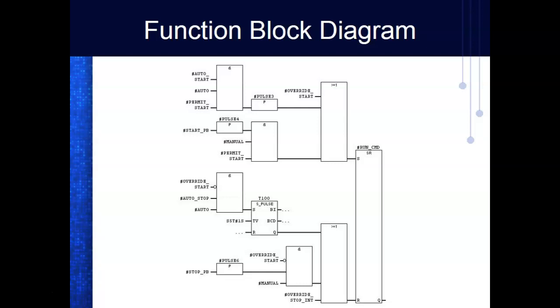So basically, PLCs don't program in the ANSI symbols because it's not international. They program in what we call the IEC symbols, but it's still digital. When you learn about ANDs and ORs and NANDs and NOTs and counters and everything, you'll understand this language. So if you came up through that trade, then you have a method of programming a PLC.